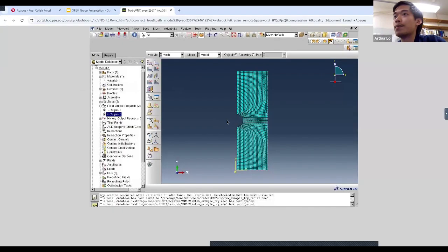So moving on to the mesh, like I was telling you earlier, there are different regions where I had different mesh densities. So you can see that the central region has a denser mesh compared to the outlying regions, because that's where we expect the crack to initiate and propagate. So that's why I generated a denser mesh in the center, but a coarser mesh because we're not as interested in those regions relatively, since we don't expect cracks to form there. So these are all standard quadrilateral elements.